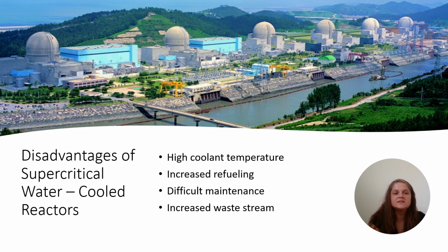The single-phase steam flow transport of radioactive materials from the core to the high-power turbine can hamper maintenance and inspection of the turbine and increase radioactivity dosage to staff. So the last thing with the supercritical water-cooled reactor is the fuel assemblies contain more parasitic materials than those existing reactors. So this increases waste stream.